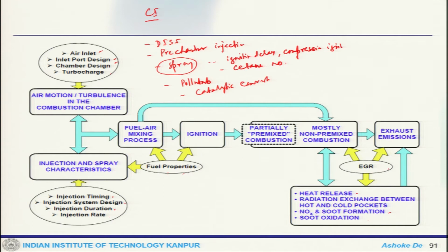So, EGR is another advantageous technology which allows you to improve the thermal efficiency of the system. It inducts back some of these exhaust gases to the fresh mixture. So, EGR allows you to control the temperature of the incoming mixture or the reaction temperature also, to remain under some control where your pollutant formations are not that high.